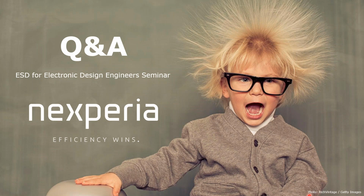The reason is that the relative deviation of the capacitance of the devices is more or less the same whether you have a 20 picofarad device for CAN, or a 2 picofarad or 1 picofarad device for gigabit Ethernet. Let's say you have 10%, then you have a maximum deviation of 2 picofarads for the CAN device, which might be problematic because of the asymmetry.